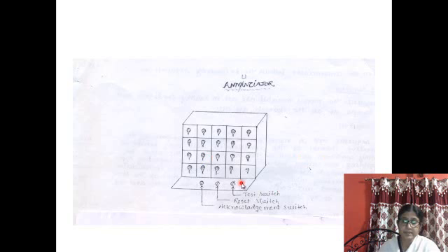And another sequence is the test sequence, in order to check the healthy condition of the annunciator. So these are the typical steps. These five steps should be maintained for an annunciator. There is another sequence of operation called the ring back sequence, where there is auto correction. That means whenever the process control loop is back to normal, that signal will be transferred to the annunciator unit automatically, so that the reset action can be performed.